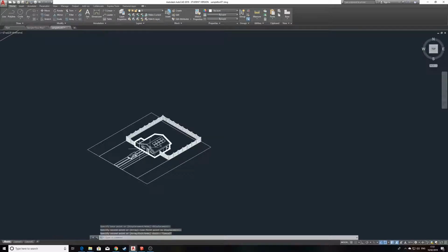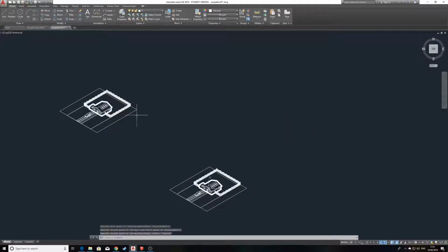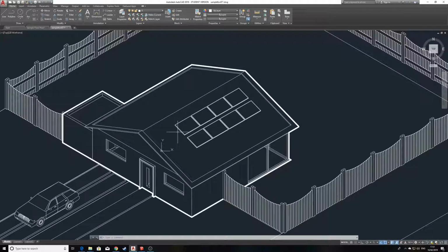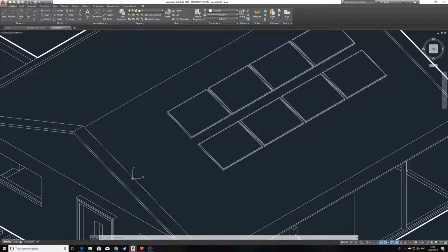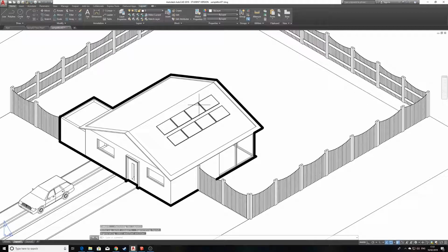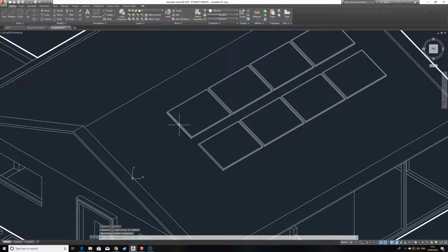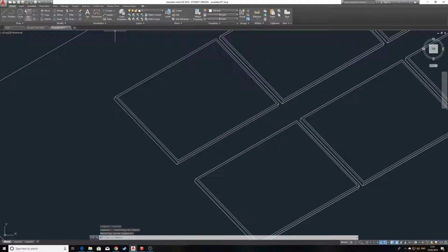So if we mess up a drawing, we know we still have this guy here, and we can edit on that instead. So let's say our first diagram will be, we just want to highlight these solar panels so we can talk about the sustainability of the building. We'll go in again and do the same idea. We'll select polyline and draw around this solar panel, and we're just going to hatch it. We're basically going to color it in blue, just to draw emphasis to it.